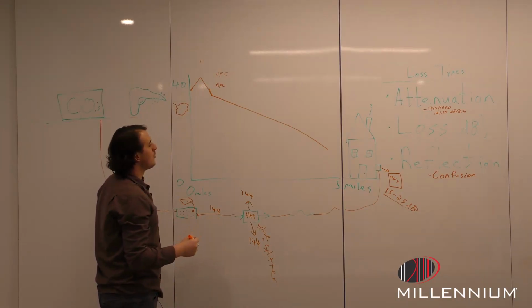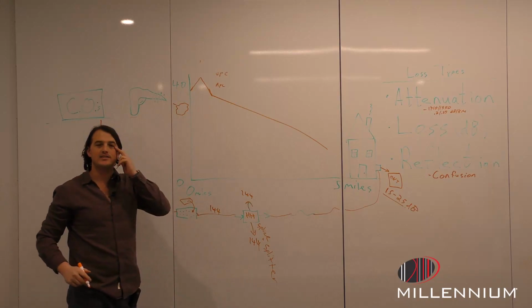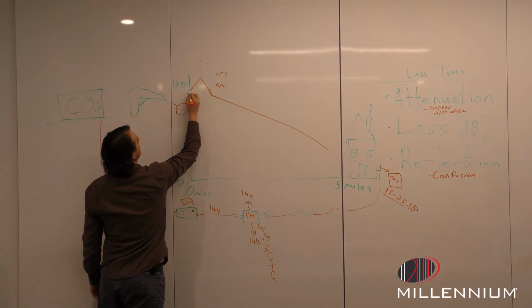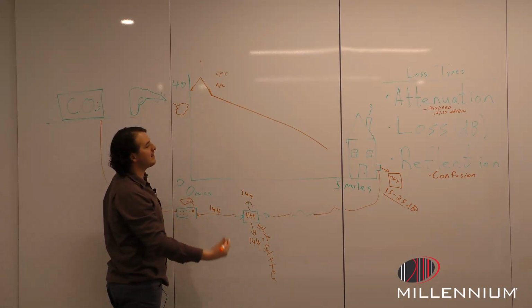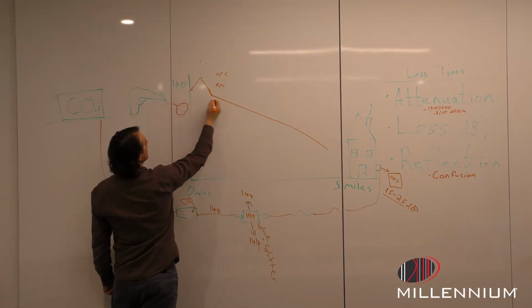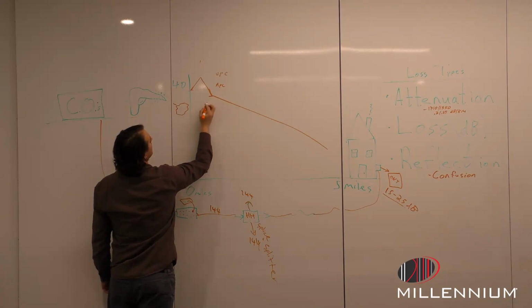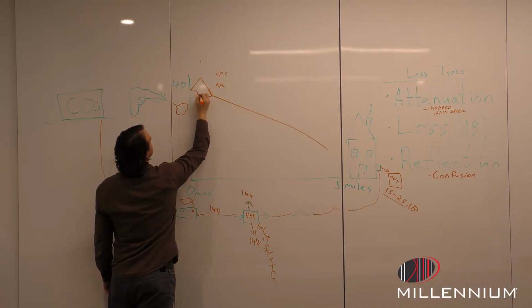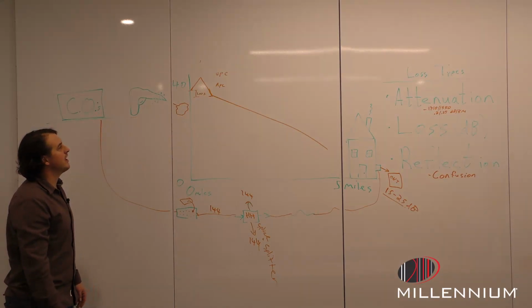All right, so with our connectors, we have a reflective event, but we also have loss associated with them. And that difference is right here. So we're starting at 40 decibel power. And just by adding that connector, in our analogy, we might be losing 1 decibel power. But the measurement from here to here, this is also loss. That is the loss associated with that connector.